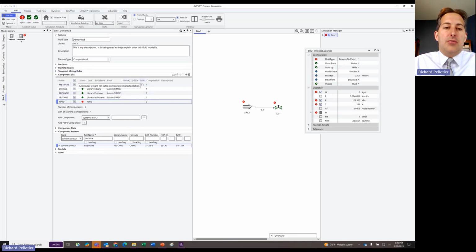And you need 2 of the 3, or preferably all 3, to be defined in order to satisfy the definition of this component, right? So if I come over here and I provide some values, and once I provide 2 of the 3 values, you can see this turns green, and now this is satisfied.